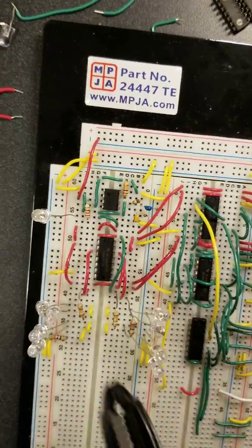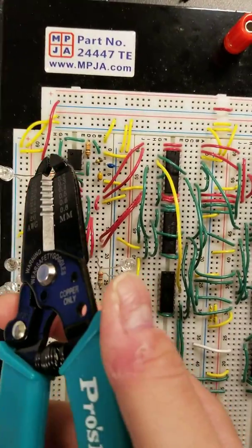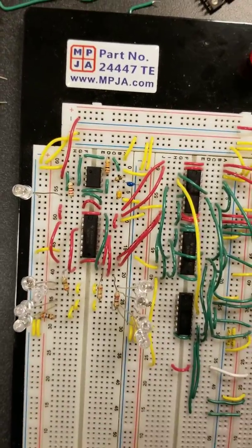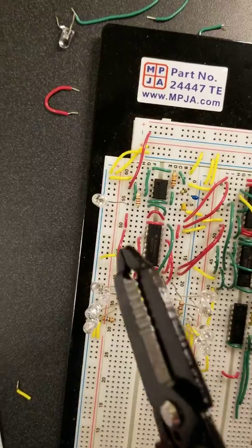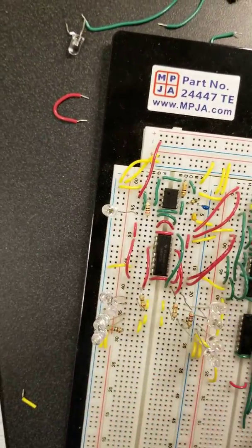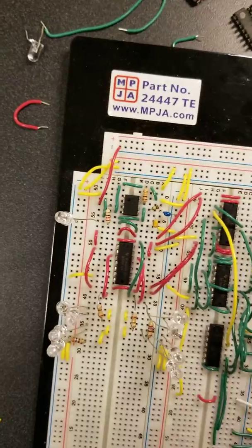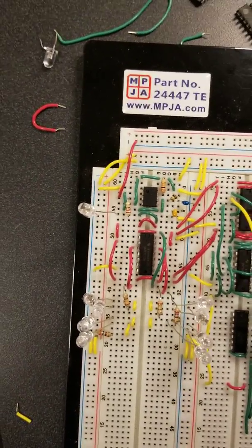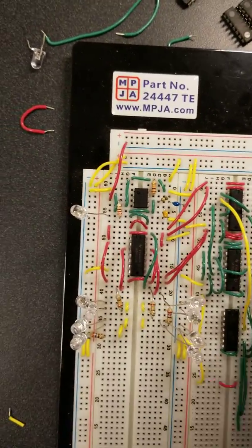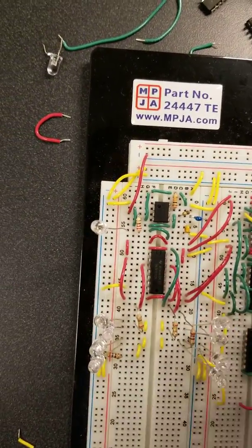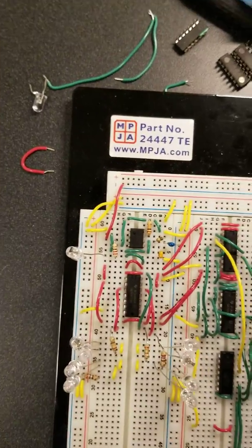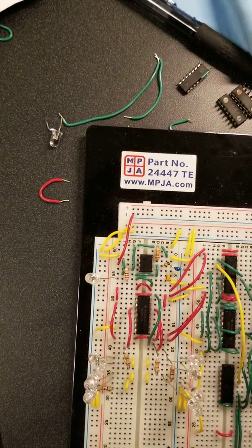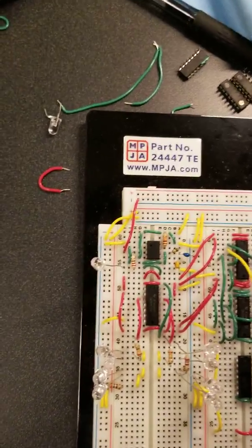This is just a 555 timer. I made the clock speed slower because it'll be easier to see. Generally, the clock speed for the register in charge of the main FSM would be faster, and the clock speed for the factored FSM part would be slower. But those would be found out through experimental runs.